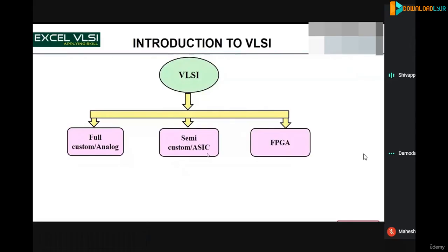The difference between ASIC and FPGA is that FPGA is field programmable gate arrays. I think many of you know this. ASIC is one-time programmable, or rather you manufacture one time and build a product. And if the chip doesn't work in a product, you will have to just throw that IC away. But with FPGA there is a possibility of fixing the issues by reprogramming the logic within the device. That is field programmable gate arrays. So you will see pretty much these three kinds of semiconductor designs in the industry.